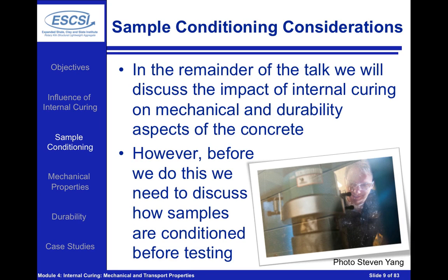But we also need to remember that how we handle the sample before we test it can be very important to the properties that we're going to measure. So we want to talk about how the samples are handled, because many times we may think, well, we just put our samples into a water tank and then we want to evaluate those properties. What I would actually ask is, does that really represent what we're getting from a concrete that may be in the field?